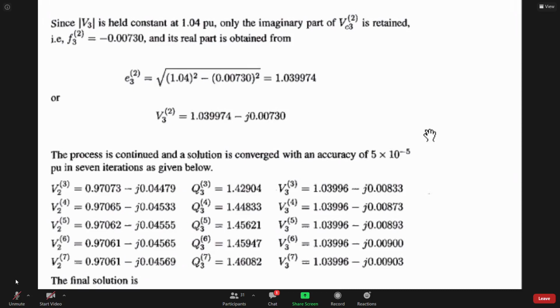Actually, as I have already mentioned, the power equation is a nonlinear equation, right? So a nonlinear equation requires an iterative solution. You cannot find the result by regular linear calculation. Sir, it is very time consuming. Yes, it will be time consuming, that's the correct response. But an iterative solution is necessary for the power flow equation. You cannot bypass that.